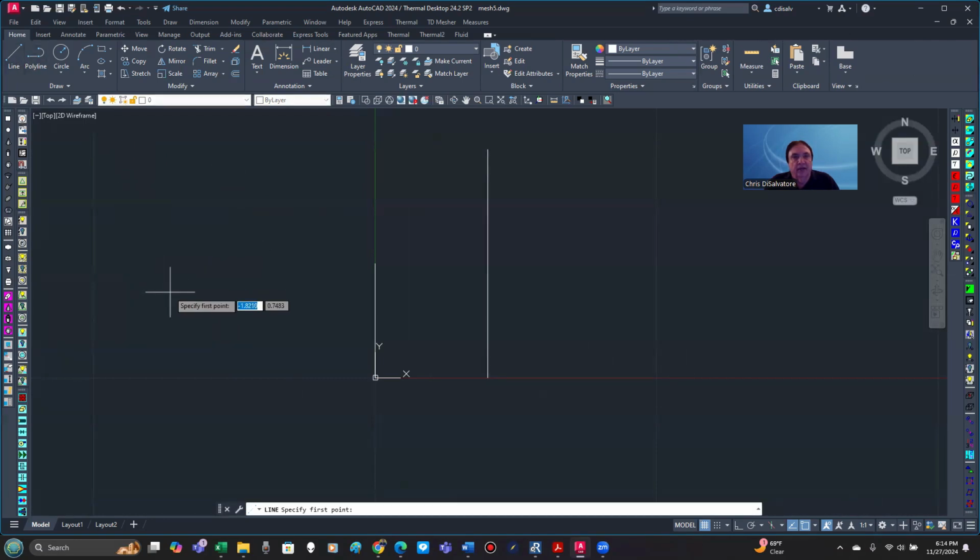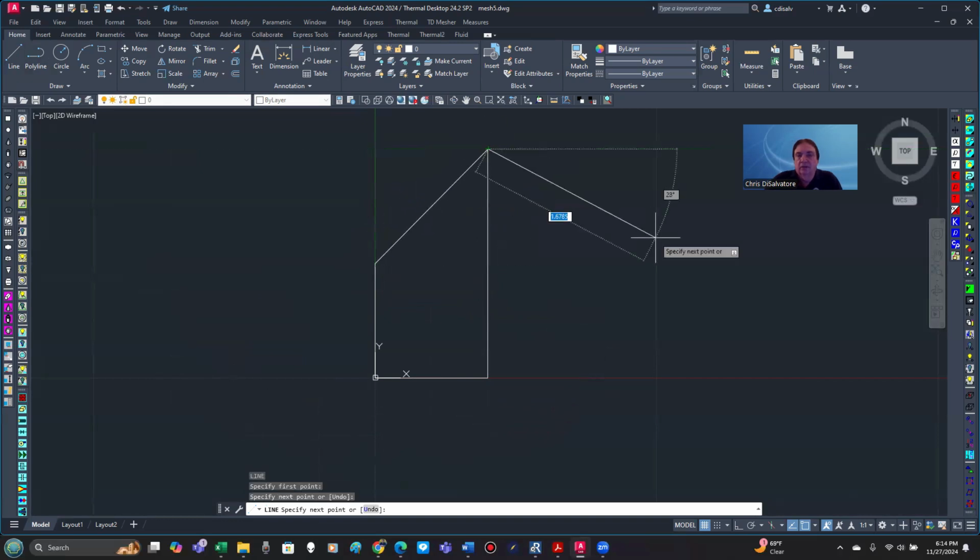I can select the line command. And if you have clearly distinct features already, and you're going to generate a line, go ahead and click at the end of the lines, and you'll be able to enter your line that way. I'll hit enter to get out of the command. Or I could have done the same thing, entering coordinates there. Both ways will work. So I'll go ahead and hit enter and go back into the line command, and I'll close up this feature on the top.